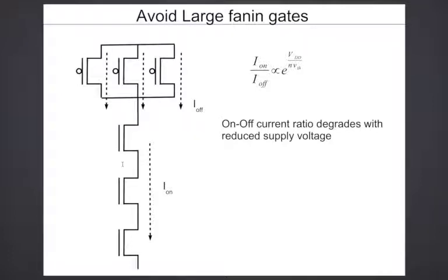When you do that, the area occupied by the gate becomes smaller, and you can also get some benefits of speed as long as the number of inputs is reasonable. That is why you find in standard cell libraries a variety of gates. You might have hundreds of logic cells, with a large number of inputs and complex Boolean functions implemented in the same gate.